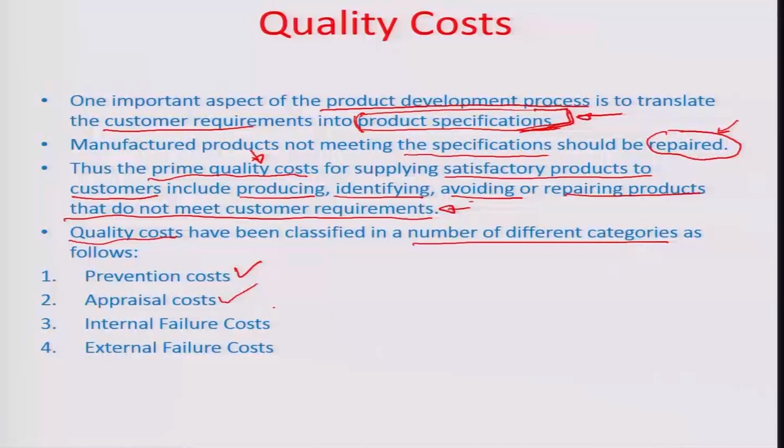There is also something called an internal failure cost, which has to be absorbed once a system has been already partially built. Let us for example, look at a car making facility. If you have already produced a weld body just up to the final stages, and then you realize that you have a spot dent, then the whole body is lost, and it is an internal failure cost which comes to the business in fact, and then either you have to somehow repair it offline, or if repairing is not possible, then scrapping it would mean a humongous amount of metal has already been wasted, which goes into the car body.